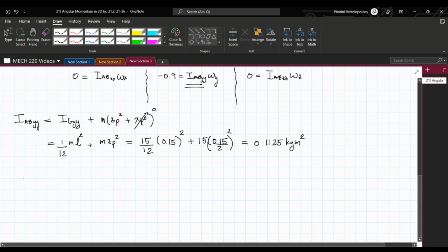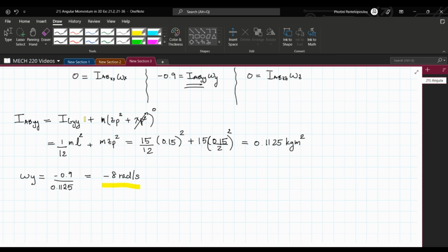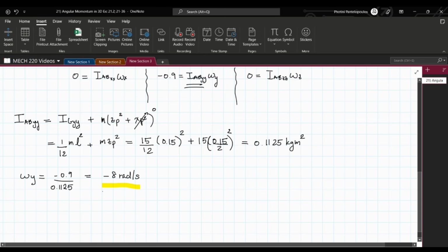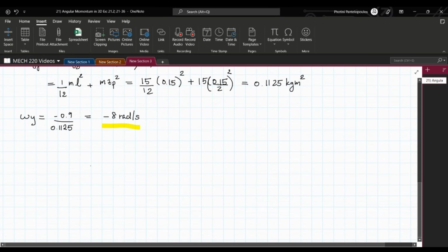And finally, we can use these values to solve for the angular velocity of the plate at the impact. Now, this is only the first part of our problem done. The second part of our problem aims to actually answer the question. So we needed the initial angular velocity of the plate in order to use conservation of energy to find the angular velocity of the plate after an angular displacement of 180 degrees. So this is essentially why we used angular momentum to find the angular velocity of the plate just after the impact with the bullet.